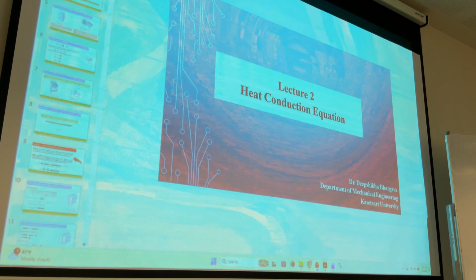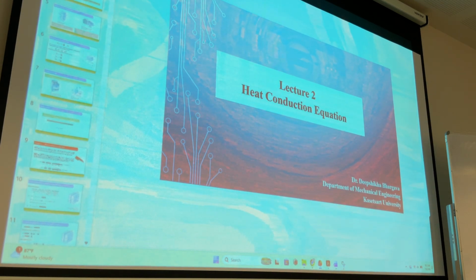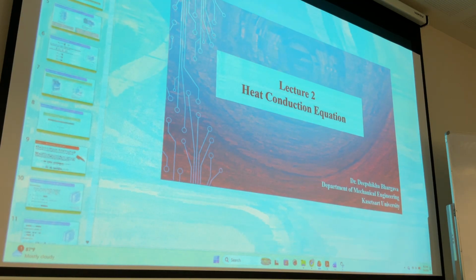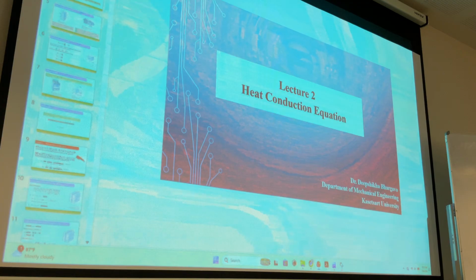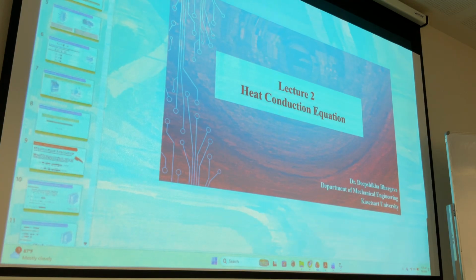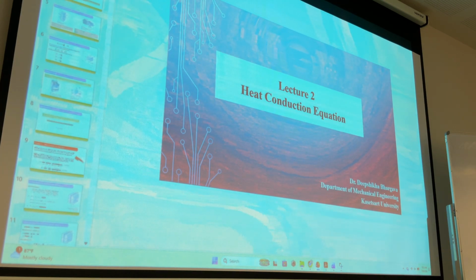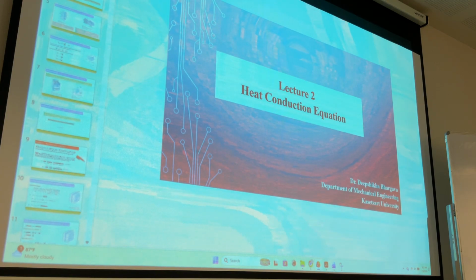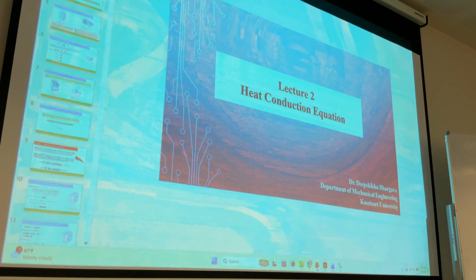And in the second chapter we are studying heat transfer by conduction in detail. Okay, so we are first studying heat transfer in different shapes. All sort of heat transfer in any object can be classified in three categories, in three shapes. It's either going to be a plane wall or a cylinder or a sphere. If you are studying heat transfer in a window, in a glass window, you can consider it as a plane wall. If you are studying heat transfer in a bottle, you can consider it as a cylinder.